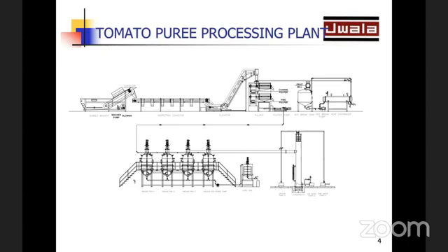Now this pulp is very thin. It's not viscous at all. The concentration is just 4 degree Brix. When we say 4 degree Brix, we mean just 4% solid content and 96% water. So the product is fairly free flowing. It is not possible to sell a product with such a high water content, because essentially we want to sell the solid content of tomatoes, not water.